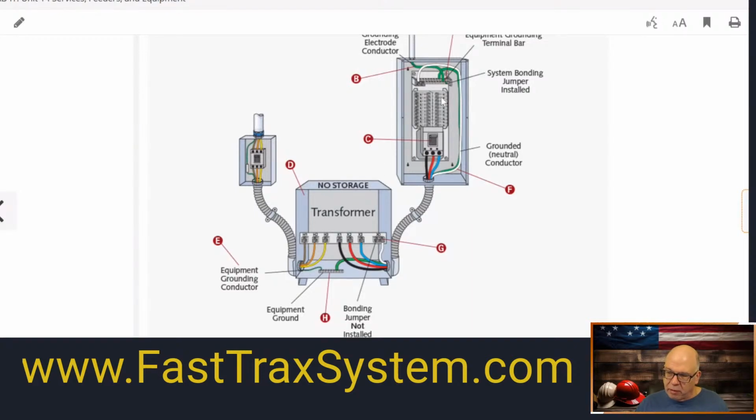This protects the panelboard. That's required in 408, so you can't get away from it. People ask me all the time, can I come and hit a panel with no breaker? No, not in normal applications like this. You're going to have to hit an overcurrent protected device, because if it's a panelboard in here, that's the guts, then 408.36 is going to require me to protect this panelboard. So for all intents and purposes, you're still going to have to meet that rule and have a breaker in there, okay? So in that case, this breaker is rated 225, then these conductors have to have an ampacity of at least 225.